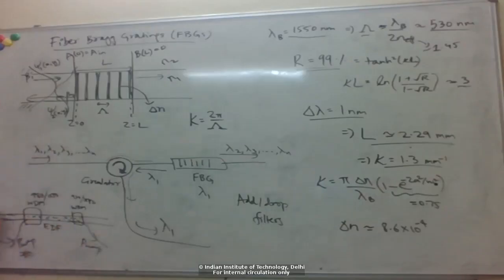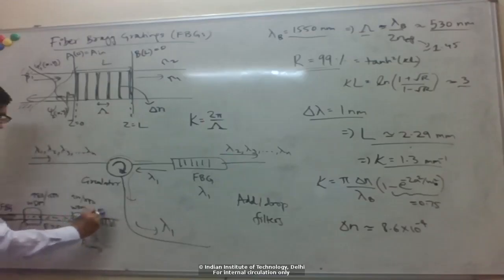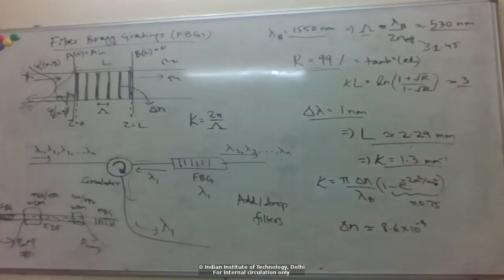And then from where your signal is coming, that needs to be amplified. Or in this case, you're building a laser, so actually there's no input signal, right? If you use it as an amplifier, as we already studied, we have a weak signal incoming that we amplify. But if you want to build a laser, what we do is build FBGs into the same fiber on both sides, okay? And you can design this to operate at whatever wavelength that you want to lase at. So for example, if you want 1550, then you can have these reflecting at 1550.